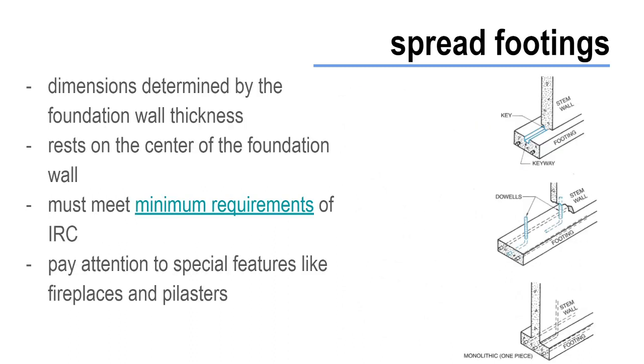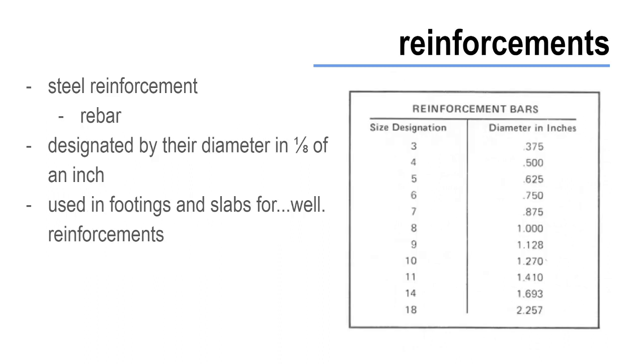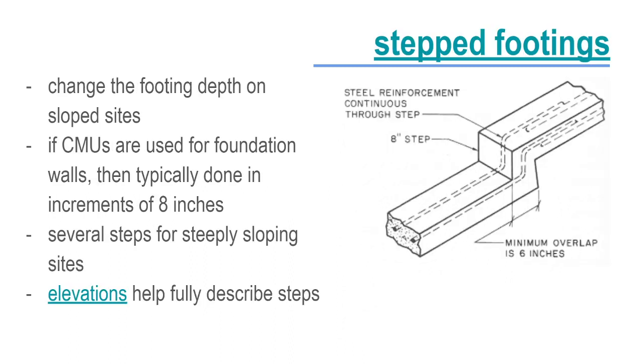And so we can see here in our footing, we have rebars running horizontally to help keep it supported. In your foundation wall too, you may have a grid of rebar, or you may just have vertical rebars to help tie it in, to help keep everything nice and supported. And we use it for reinforcements. And if I had a slab foundation, I'd have a grid of rebar, which I'm pretty sure I have a slide in either the next one or a few coming up that shows that.